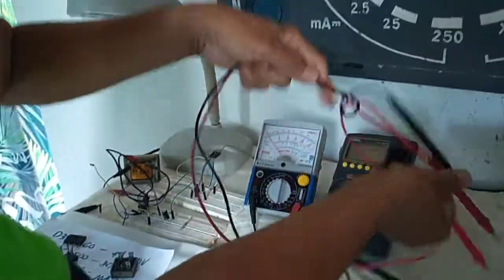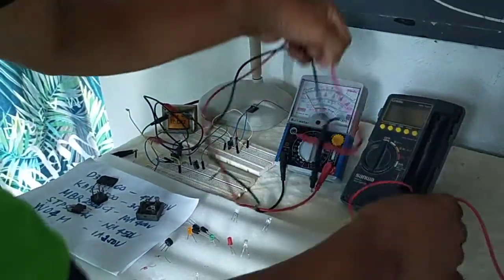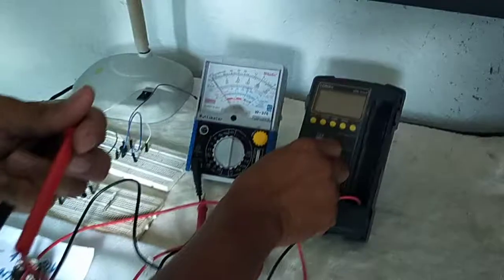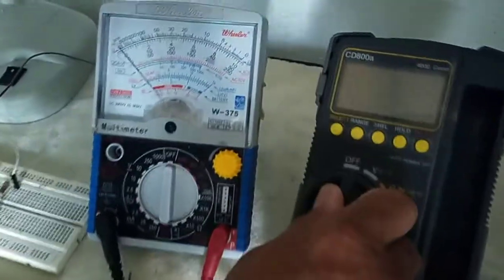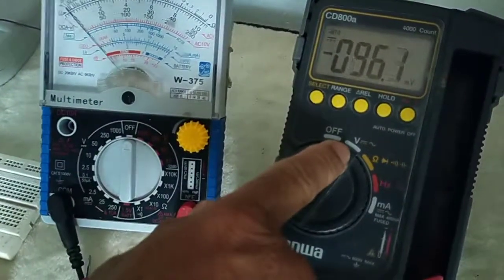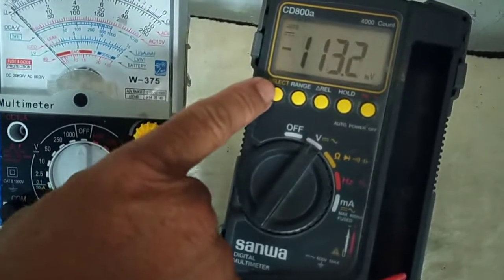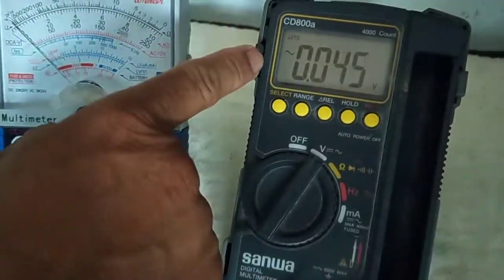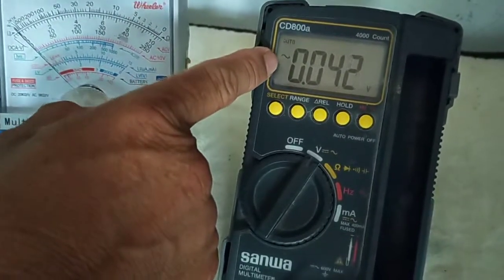that provides DC voltage. So when you measure the voltage of this battery, we have to set the range selector switch to voltmeter. Then select whether it is AC or DC. If we press that one, that displays the AC.